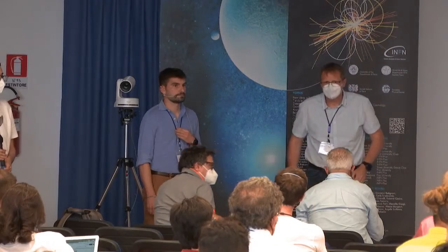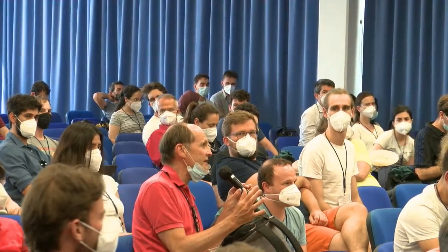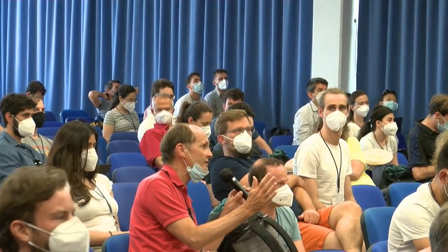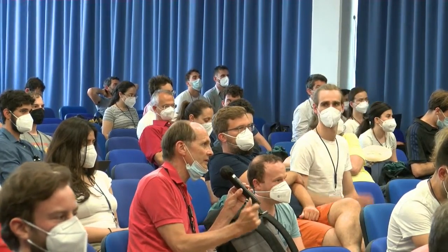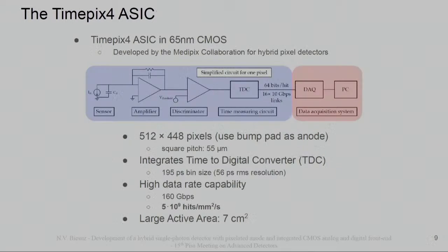On the time correction, the rise time you expect in the Timepix is several nanoseconds, 5 to 10, and then you have to correct that to 10 picoseconds. Well, the rise time here really is determined by the MCP signal alone, because you basically use the metal pads on the Timepix for the anode, right? So the capacitance there will be small enough to be negligible.